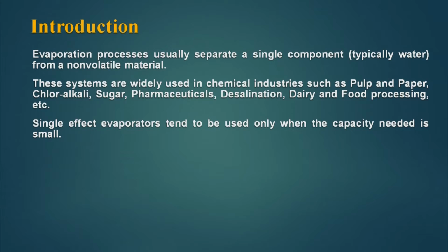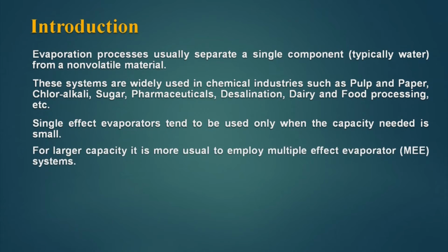Single effect evaporators tend to be used only when the capacity needed is small, and for larger capacities it is more usual to employ a multiple effect evaporation system, because the steam economy in a multiple effect evaporation system is quite high.